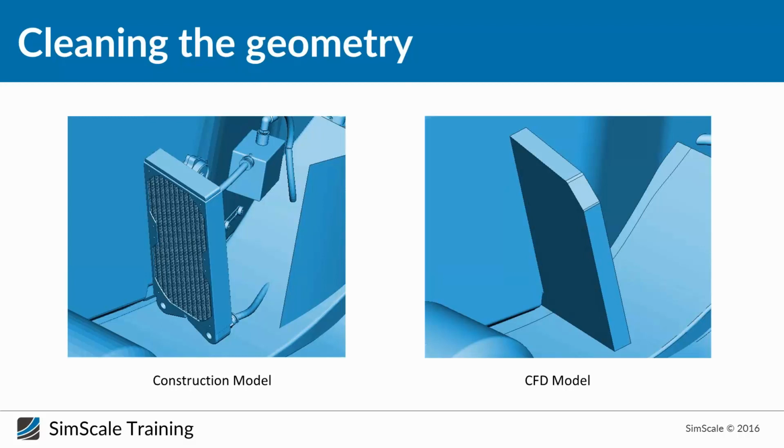I mean, you will not get the same accuracy of the surface as here using the mesh. So we have to do another simplification of the radiator, as you can see from here. The radiator here is represented with a porous media, just creating a three-dimensional shape that will represent the radiator, based on the porous media that we have covered during the previous workshop.